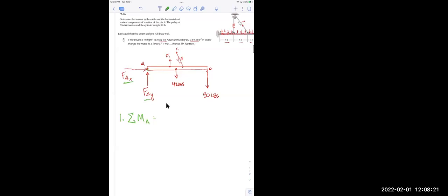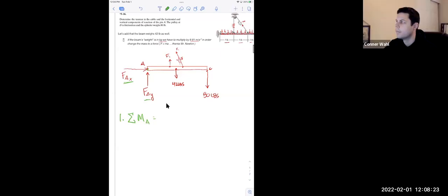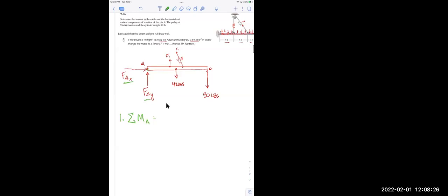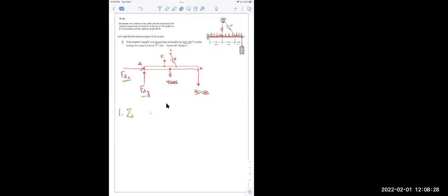Now maybe I'll end up with an equation that doesn't have anything else. Now, can you appreciate starting at B would have been kind of a poor idea? That would have eliminated the 80, but I knew 80. So I don't really necessarily need that to be eliminated. I'd just as soon have that. And so then I will have a force of AY. Maybe I'll have a force of AX. Well, maybe not, because force of AX is pointing right at C. So I'm going to have force 1 and force of A, and I'm going to have two unknowns in it again. So I don't want to do this around B. So there's kind of a bit of an art to this.